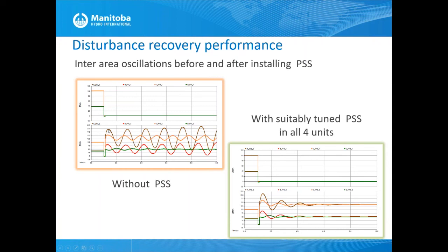So when the angle deviates, it comes back because of the sync torque. But in this situation, it comes back, but it gradually keeps on growing. That's because you don't have a damping torque component. So synchronizing and damping torque, that's how it works. If you have poor synchronizing torque, it will go unstable from this point. At this point, it goes unstable.